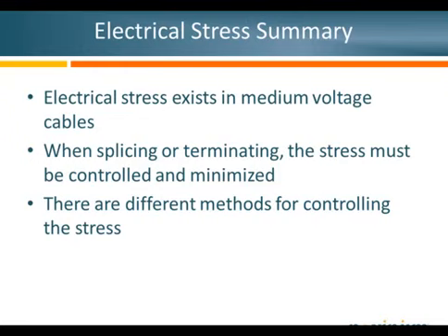So a summary of electrical stress in medium voltage cables. You have that stress where you terminate the shield on the cable, and you have to control it and try to minimize it. You can control it with geometric stress control or high dielectric stress control, but you have to control it, you have to insulate it, and you have to take care of that stress. And then you want to choose the best method for your particular application.